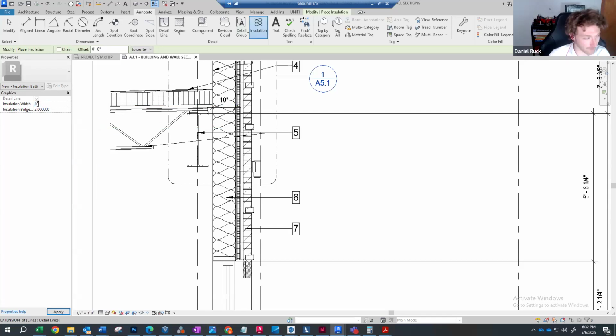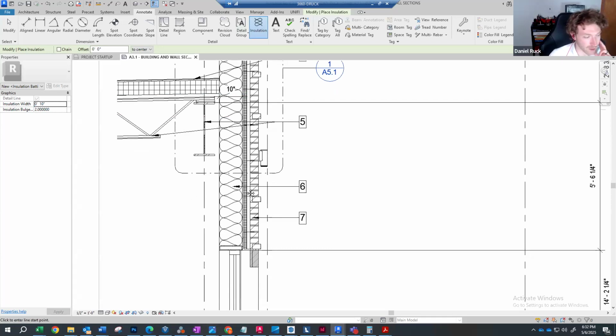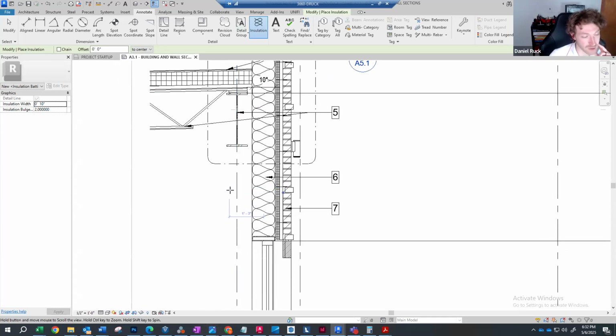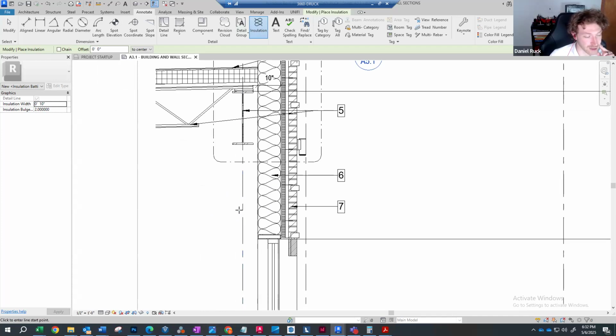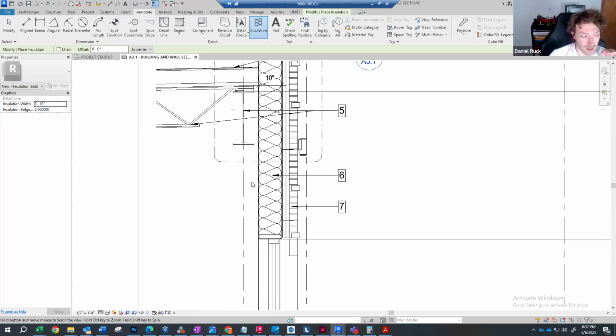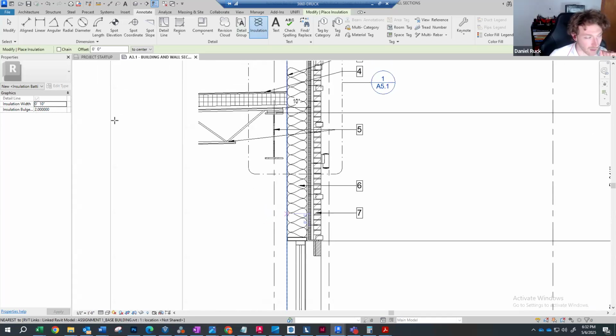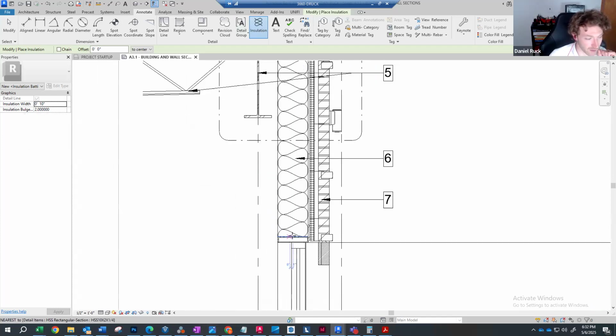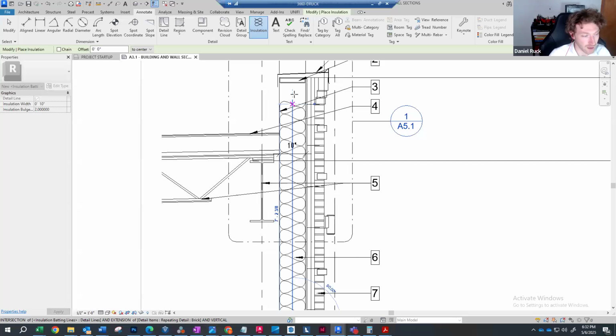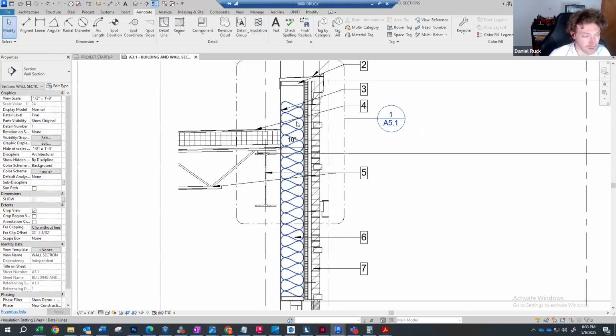So most of the time if you are working with metal construction on an exterior shallow building, you're going to be looking at 6 inches, sometimes 8 and sometimes 10, depending on the design of your facade. But you simply type in your insulation width and then you can trace it as needed and locate it within the stud.